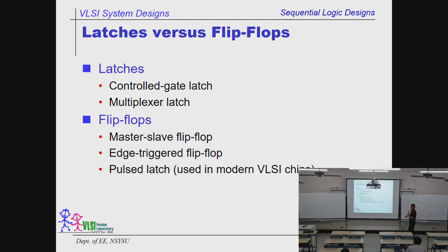And the last one is very much welcome in industry. It's called a pulse latch. Pulse latch means that we only open the window for a short period of time so that we can finish the data transmission, then we close it. That'll save a lot of power. I myself had this kind of project before.